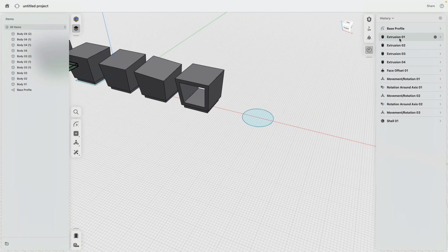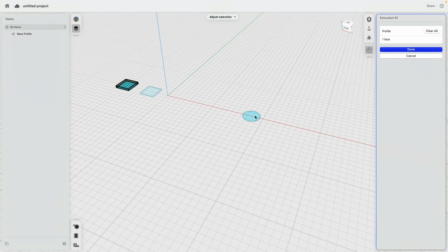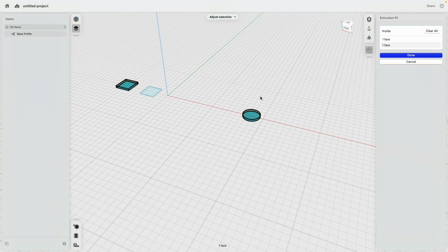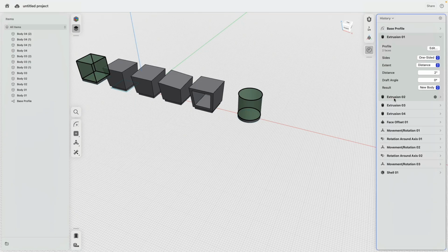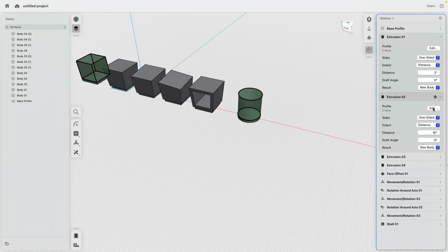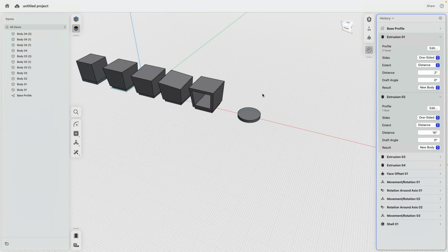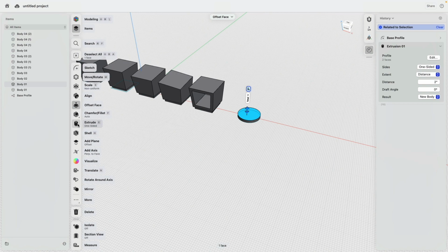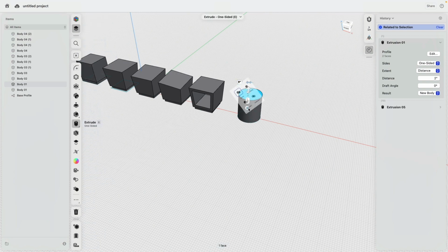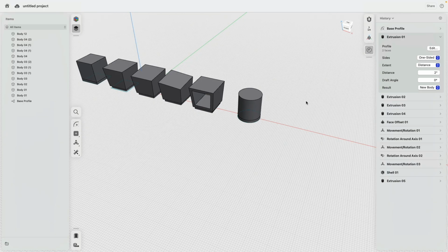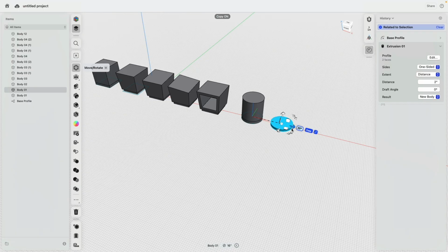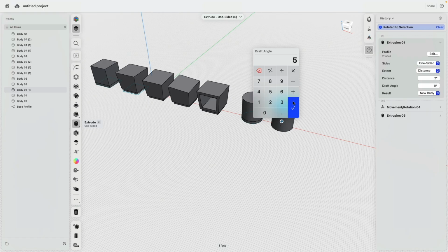By the way, I can go back to this idea and simply make sure that my bases are always 2 inches high. You see how I'm adding this to it. But I see that this one also added another cylinder to it in this current version of Shapr, so I just turn this one off. I don't want this. Let's do an extrusion, 16, tab, and new body. Very nice, thank you. And because I'm going to use exactly the same base, this time I'm selecting the base, move this one over, very good. Then I select this one, 16 up and 5 degrees.